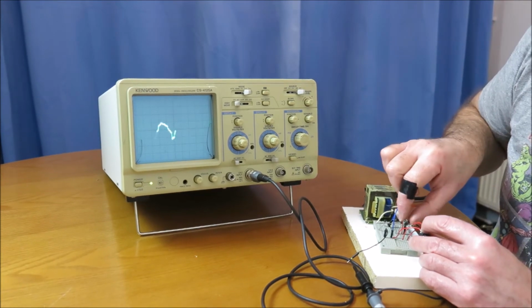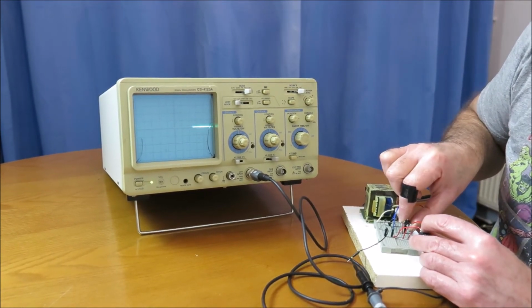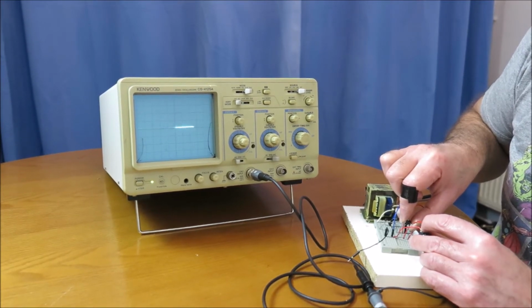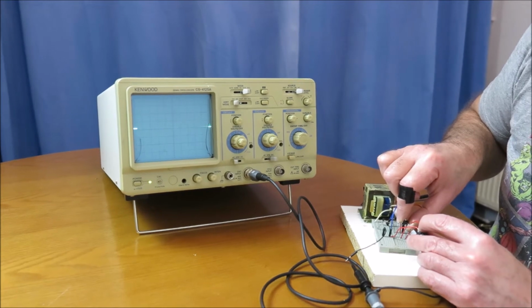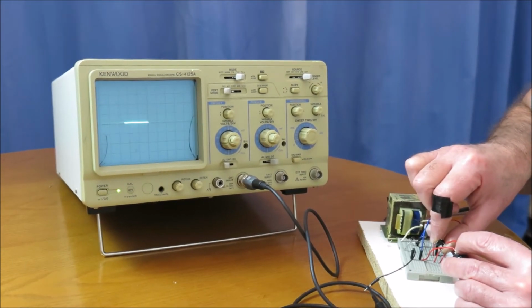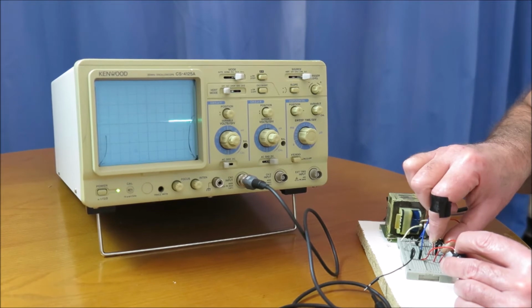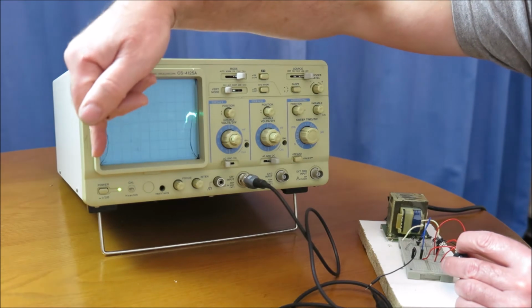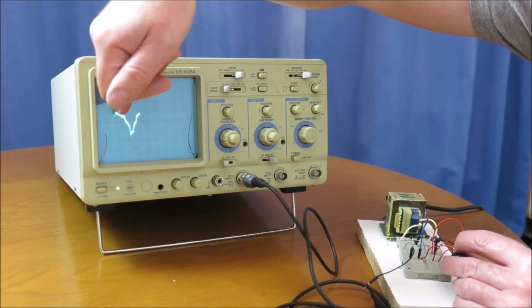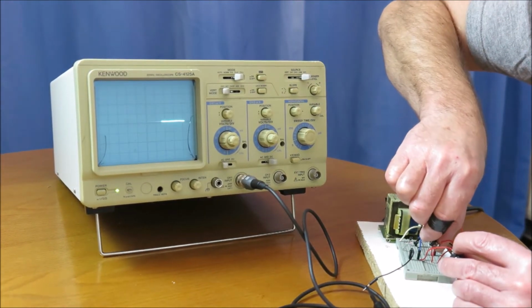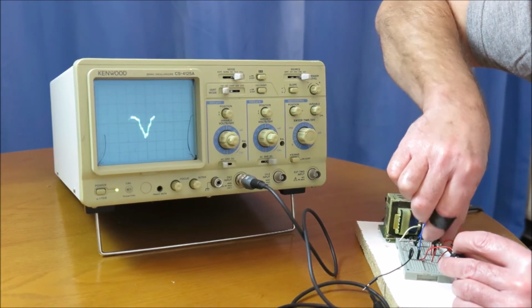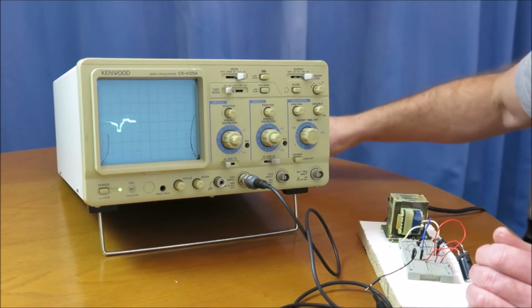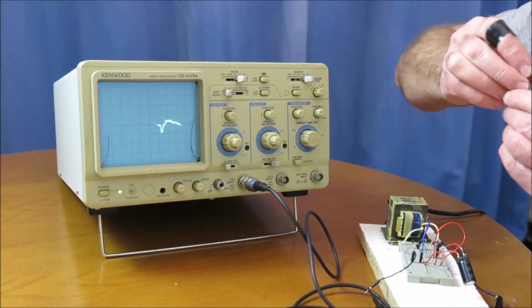Now if I switch in the capacitor, look at that, see the difference that makes? That's actually causing it to smooth. Now it's smoothing, and there's pretty much a straight line there. There'll be a tiny bit of ripple on that straight line. If we switch out the capacitor, we can see the effect that that has again. So during the discharging part of the cycle, the capacitor is feeding into the circuit to give pretty much a straight line there. Okay, so if we wanted to remove that ripple totally, we can put regulation into it.